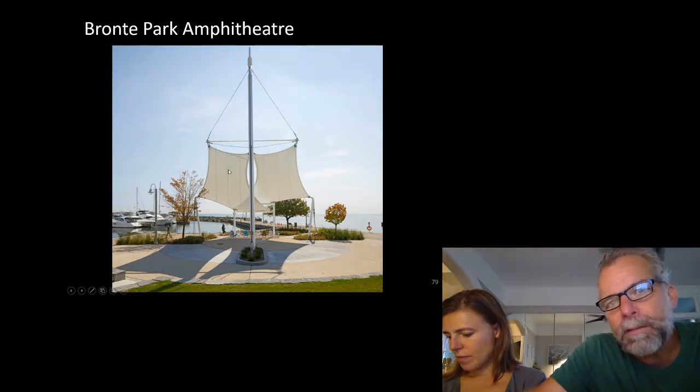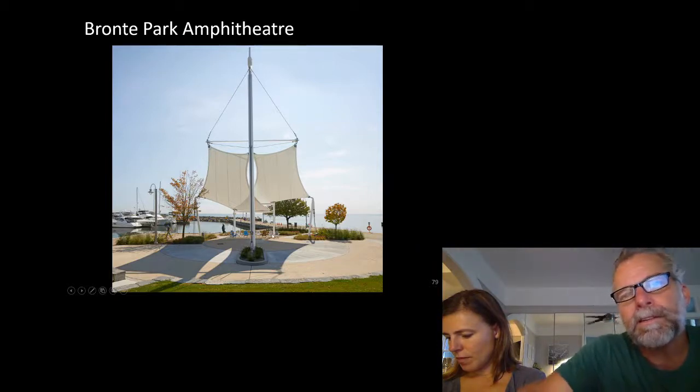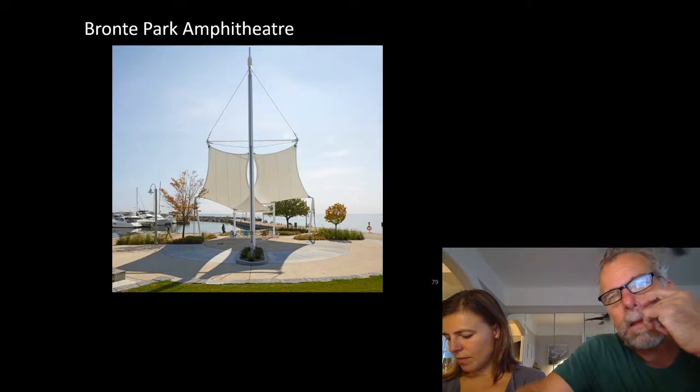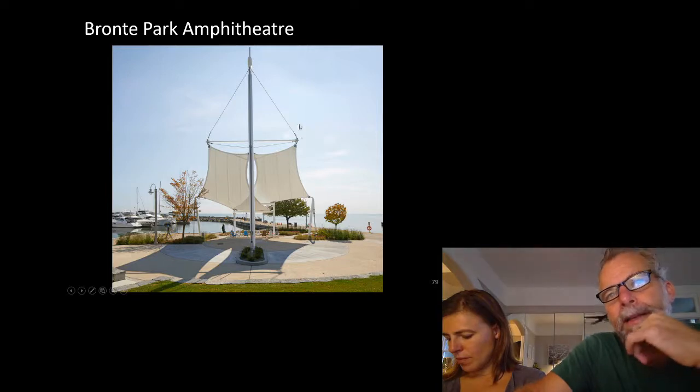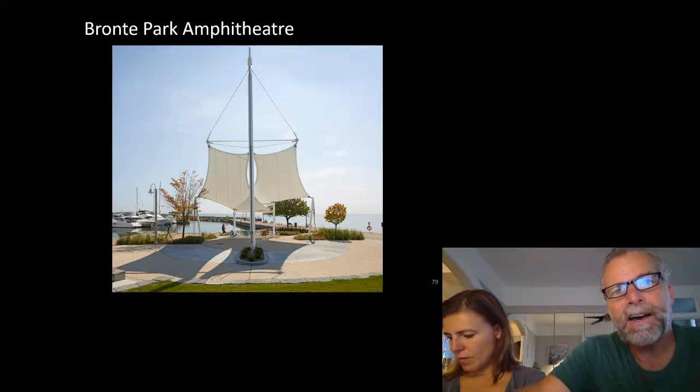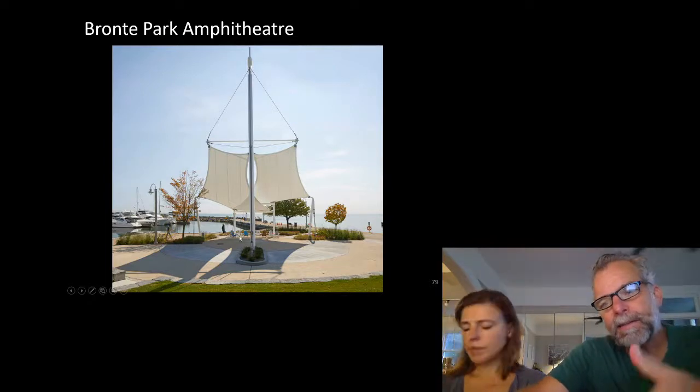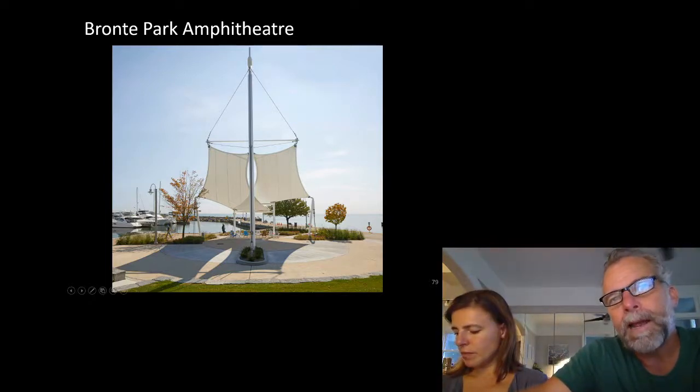Back here, you can see the membrane slopes down. That element along here is a gutter. This membrane slopes down, and there's another gutter up here. Through the bottom, from the top gutter through the bottom gutter, are a series of stainless steel pre-stressed cables at a close spacing, maybe 150 millimeters apart. The idea is that in the winter, rain will run down here, collect in the gutter, run down the cable, and form an ice screen. They've also planted down here with the idea that the planting can grow up and create a screen which becomes the backdrop for performances.